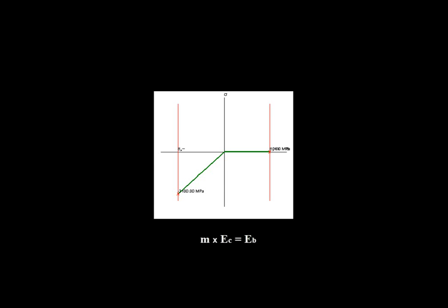If m is large, then the bearing support is less rigid than the bolts. If m is small, less than 1, even significantly so, then the bearing support is more rigid than the bolts. As m increases, the part of the bearing surface affected by the compressive stresses increases in size.